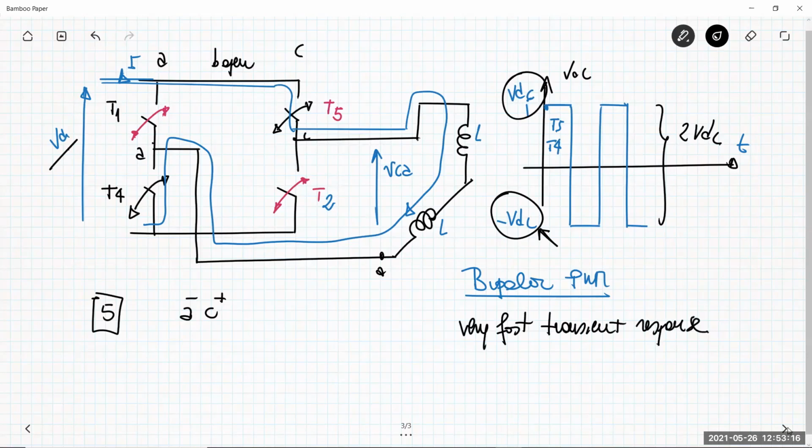Remember that, for example, in the stepper motors, we modified a little bit the L over R or the R over L driver for the stepper motor, in order to get negative and positive voltage across the inductive load of the stepper winding, introducing the chopper driver that has exactly this behavior. So this is reversible in voltage, in order to make faster transitions. This always happens when you have bipolar modulation.